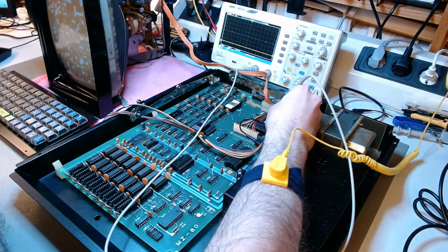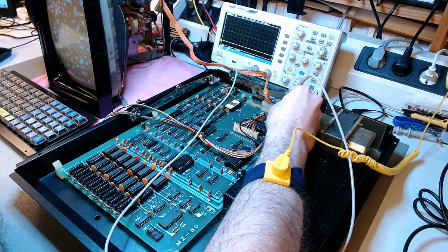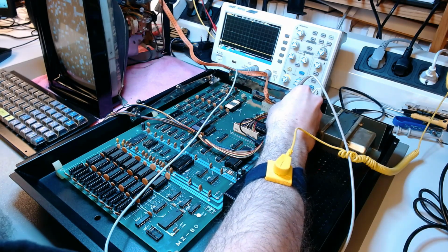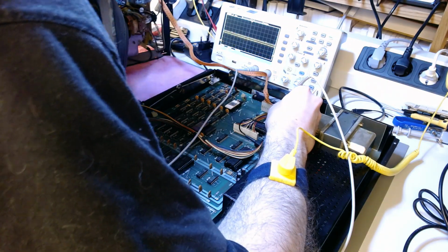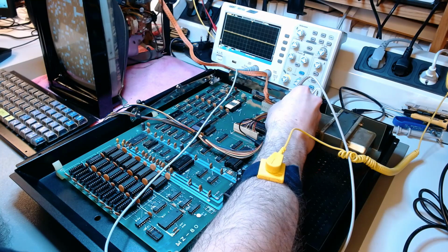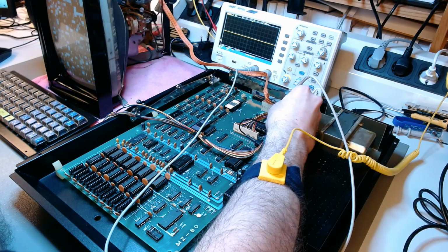So this is in constant reset. The input to this inverter gate is pin 13, which is ambiguous. It's just under 3 volts. It's right halfway. It's an ambiguous input, which is turning into a reset.